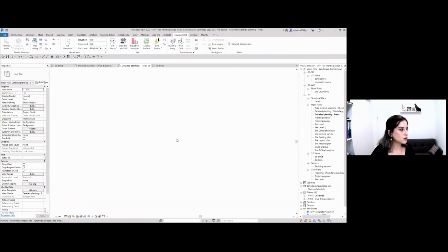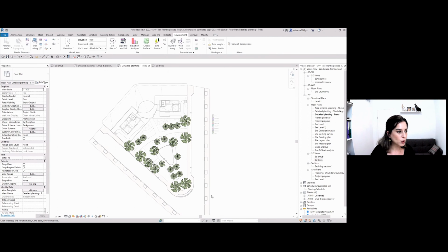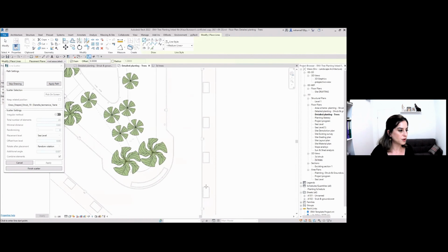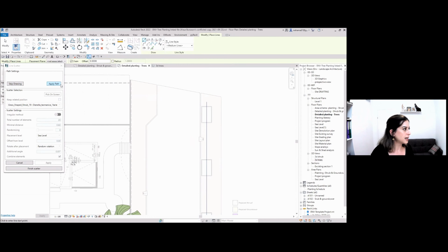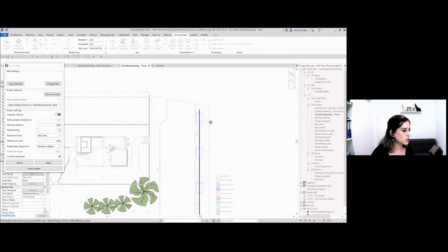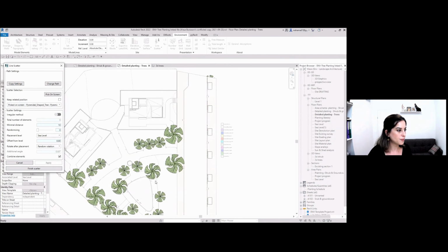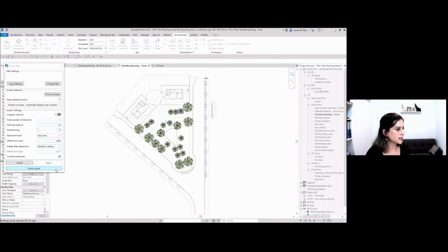And you know, this tool can be very easily used for maybe aligning lampposts or trees. So again, we can do line scatter, just draw a path on top of these planting pits of the street. Escape, apply path, and then let's just select one of these trees. Pick on screen, I'm gonna pick this tree. And then these ones should be maybe 10 meters apart. Let's do apply. Yeah, they're currently under my surface, so I don't see it. Let me just guess that it's correct.